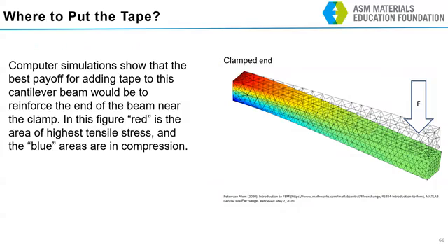Okay, so if you do the tape lab, the stress scan composite lab, our clamped end is here. This is a finite element model, so it's a computer model of how this part will move when I put a force on it. My convex side is the top side here, just like we were showing on that lasagna noodle. So the best mass efficient strategy for reinforcing this is to only put the tape up here in this red and orange zone. That's the part of the beam that's really feeling the most effect of that force.